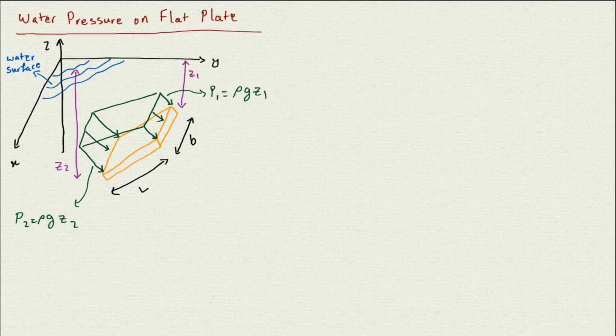So look at here, if we assume the pressure is changing on the length of that plate and it's not changing on the width of that plate, we can go ahead and convert it to 2D. So we have the 3D, and then we can convert the 3D to 2D load. To show how, I just draw this edge because assume the pressure only changes on this edge.